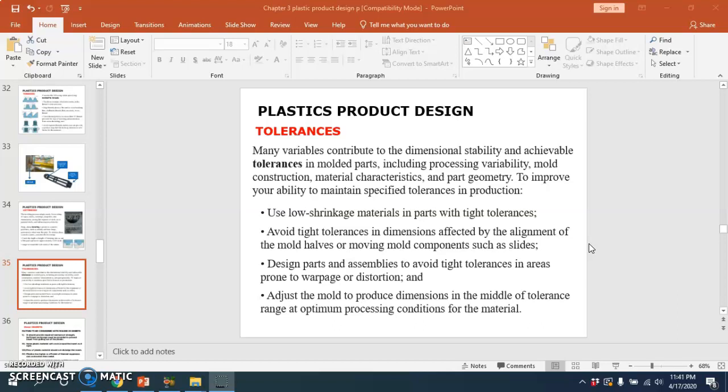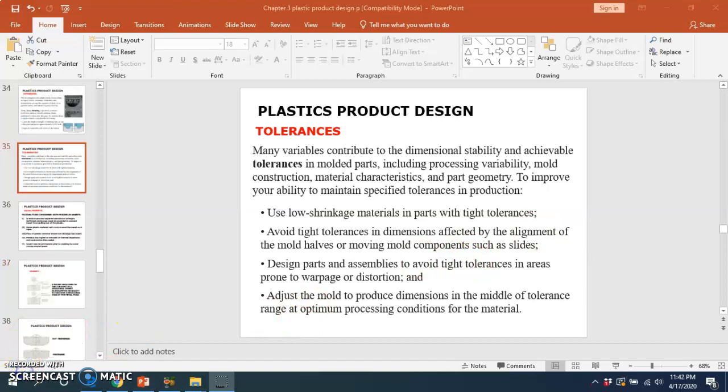To avoid unnecessary molding costs, specify tight tolerance only when needed. Generally, the size and variability of other part features will determine the actual tolerance required for any one component or feature within an assembly. Okay, tolerance is a term, or an approach, that designers use to understand how imperfection in parts as they are manufactured can still meet the customer requirement.